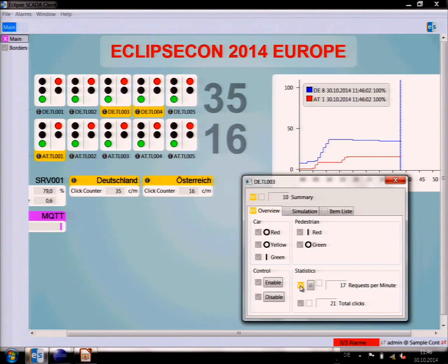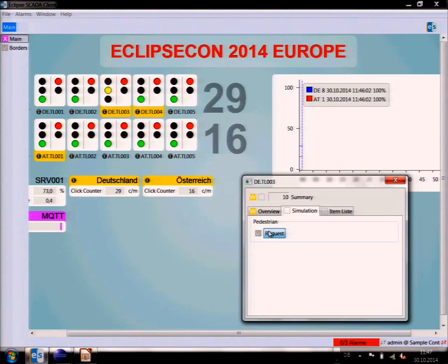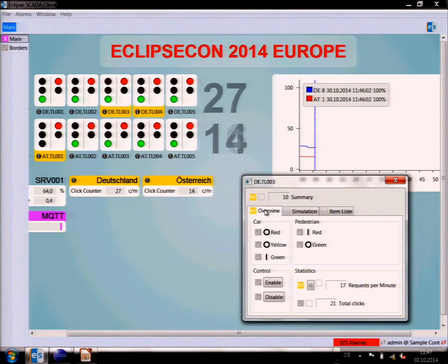Now, this is exactly what's important. If you have big systems, complex communication systems, you don't want to have all the windmills publish all the data to some broker to be sure that you gather all the values. No, what you want is a lower device, a thing which has the logic to work on its own, because if you just unplug one of these BeagleBones from the network, the traffic light will still work. If you want to try, you can unplug it. The problem is the BeagleBones sometimes don't come up again when you replug it because the power fluctuates and then the processor stops. This has happened.